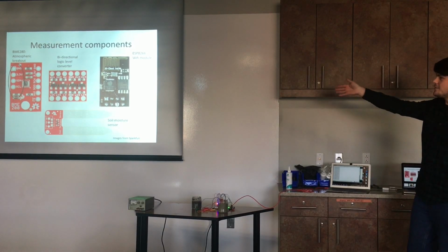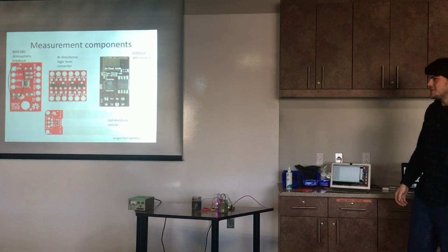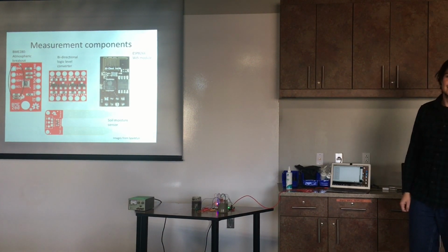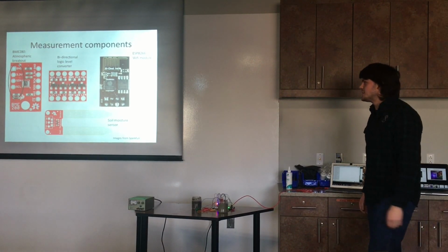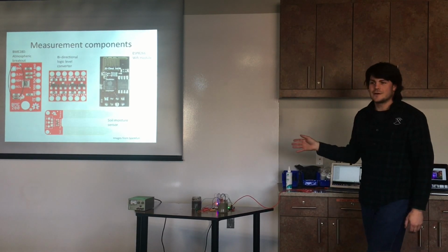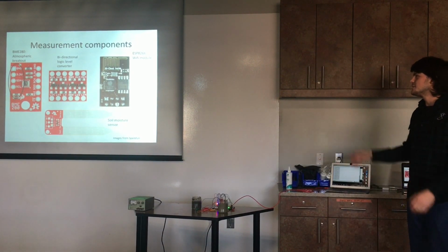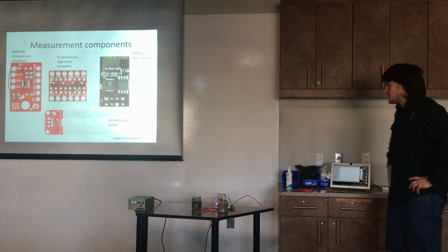The ESP Wi-Fi module was supposed to help me interface with the Internet of Things, but unfortunately that didn't work because I wasn't able to send commands programmatically. I could do it serially on my computer on the monitor, but I wasn't able to actually use the AT firmware programmatically to send data. And then the soil moisture sensor, which I have three of.